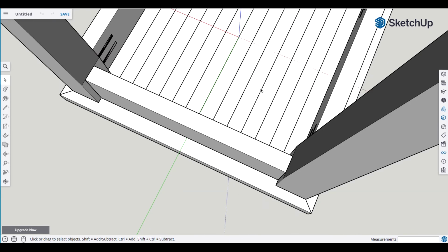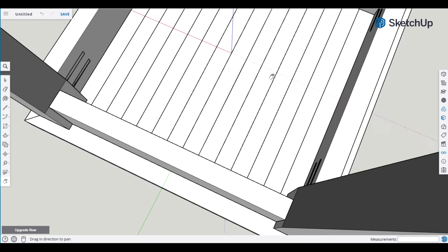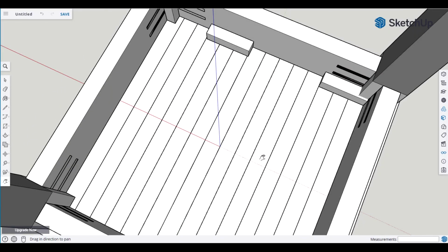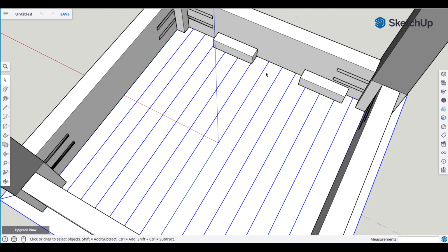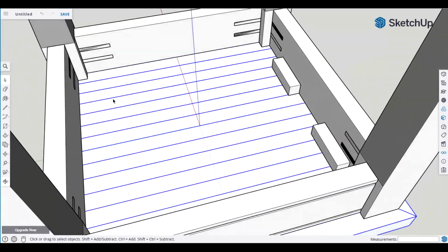So let's go ahead and zoom in, H, and then we're just going to go space bar, select, M, nudge it right about there on that red axis, space bar, and that looks okay. So now we're going to go ahead and create a copy, and we're going to move it over here.